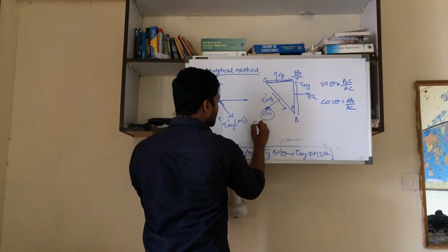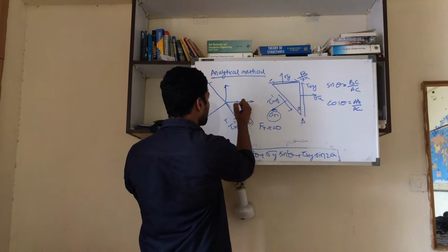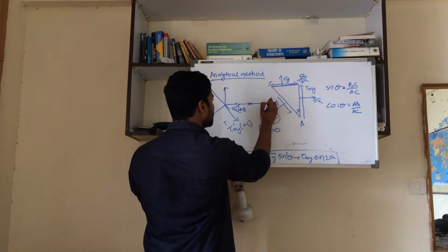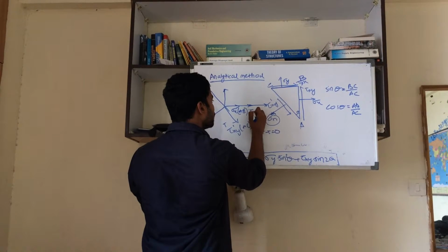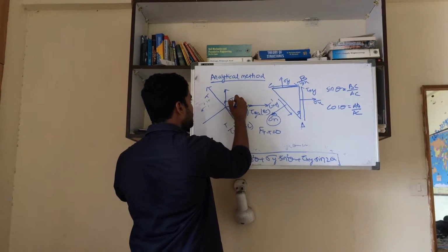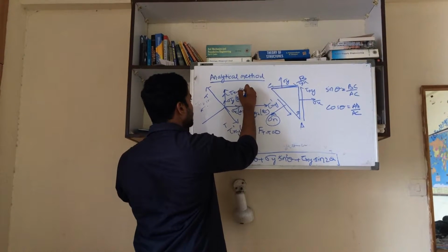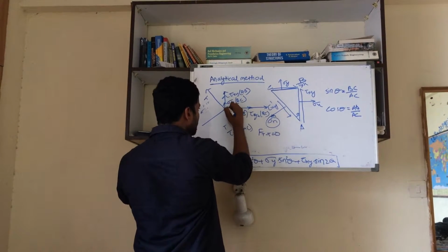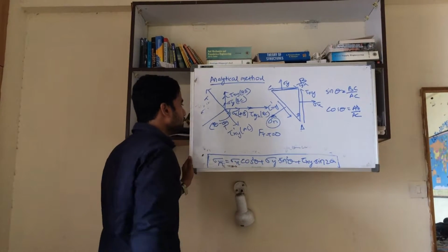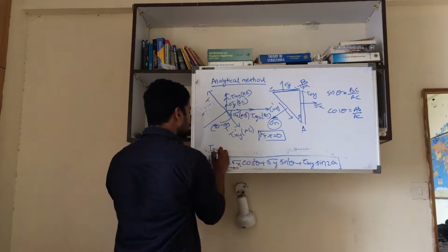I am taking the sum of forces in the tangential direction equal to 0, as before. Here I have shown sigma x multiplied with AB, tau yx multiplied with BC, sigma y multiplied with BC, and tau xy multiplied with AB. And this angle is 90 minus theta, not theta. This will be 90 minus theta. So if you take the sum of forces equal to 0, the final equation for tau xy dash you will be getting